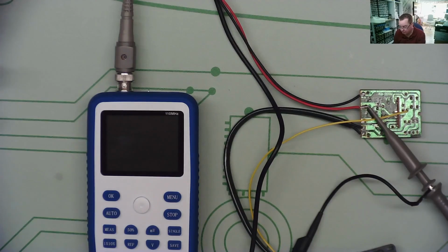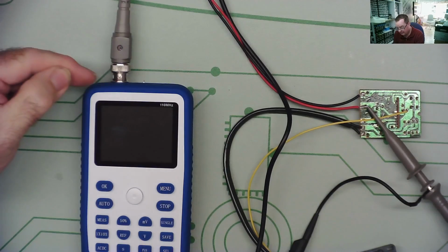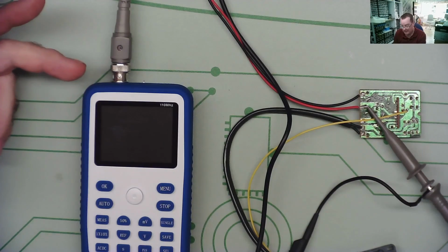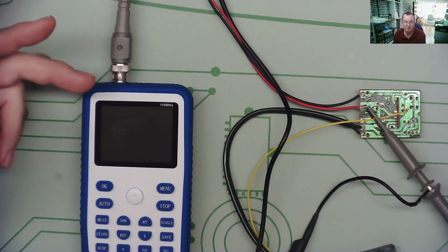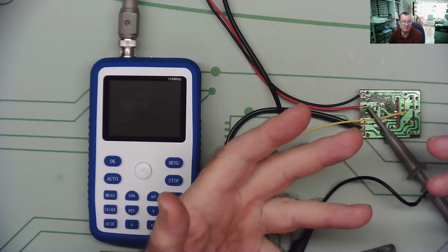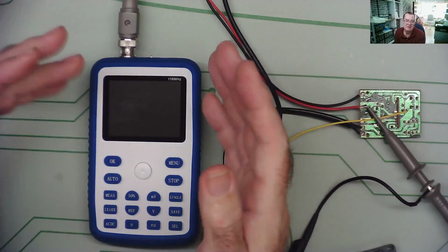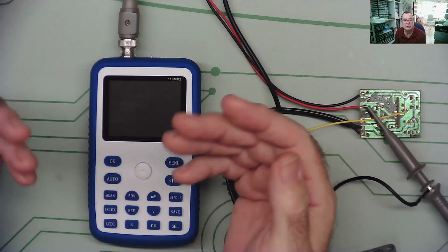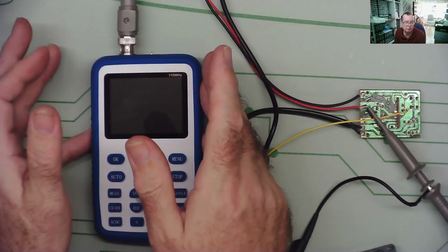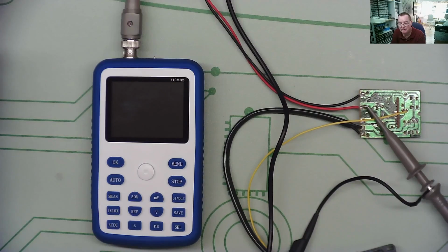Just a word of caution. Beware when you're doing this sort of thing, even with a handheld scope like this. The metal part of the BNC connector will be connected to hot ground. This will have a high voltage on, and you will certainly notice if you put your fingers on it. It's no more dangerous than working on things like this or working on power supplies. It's just a matter of understanding the risks. If you understand the risks, this is relatively safe if you know what you're doing and you know what not to do. If you don't, then really I would suggest you don't try to work on this sort of equipment until you thoroughly understand the principle of ground and hot ground.